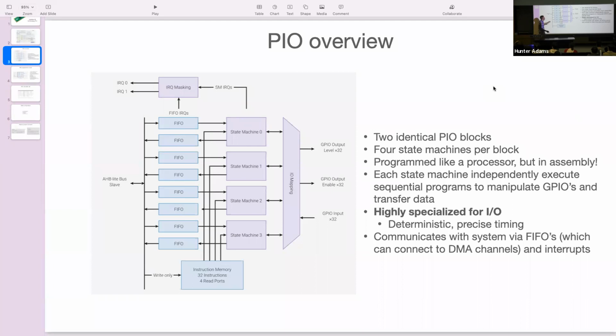In any case, they've been driving this device with an FPGA because the device requires a sequence of control inputs that have to all be timed relative to one another at 200 megahertz. It's usually an FPGA thing. And by the way, there's 30 control inputs to this thing. So we've gone through a lot of effort over the past couple of months of replacing that FPGA with an RP2040. We aren't really using the ARMs at all.